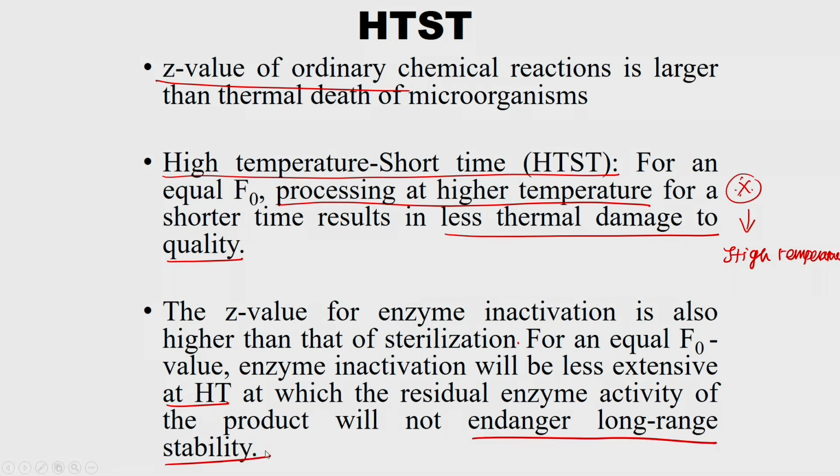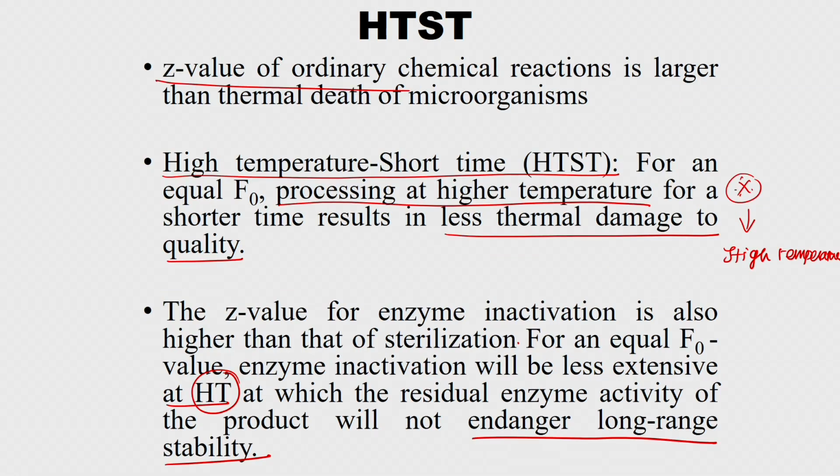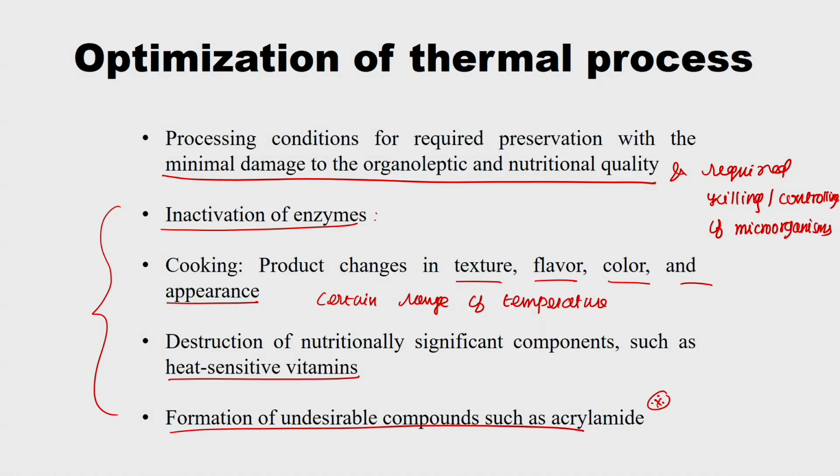This is what I told. So, I have to choose the high temperature in such a way that it should not endanger the long range stability of the product. And also, what happens at HTST, right? We have seen 4 qualities. One is inactivation of enzyme. So, this also has to be considered when you choose the high temperature.